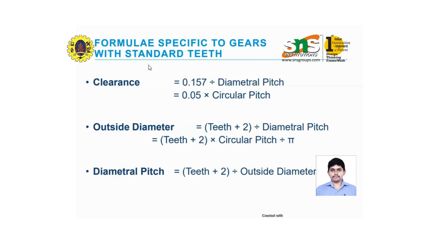And second one, we need to find out what is the outside diameter of the gear, and similarly what is the inside diameter of the gear. If you're going to find out the outside diameter, we need to calculate teeth plus 2 divided by diametral pitch. In terms, teeth plus 2 into circular pitch divided by pi. It is for the calculation of two different sizes or otherwise their tooth alignment which has been varying. It may be a non-intersecting and non-parallel element.